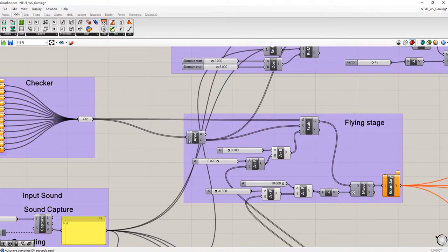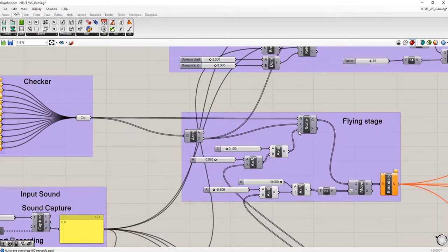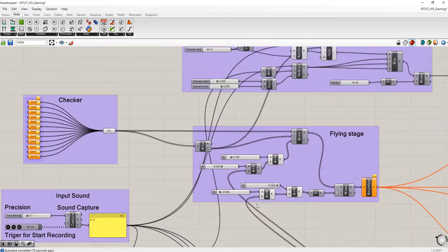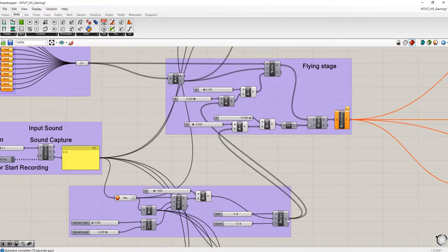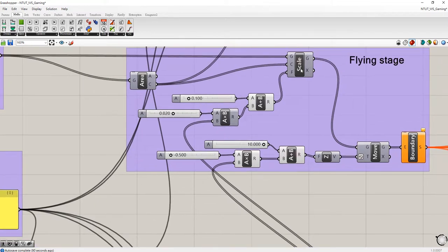So first thing, I use an area, and why I use an area, because I want to extract the center point of every curve. Okay, and then use the center point for scaling. Alright, and for the scaling factor, I do it this way. First, I connect the number to here, but I still do another adjustment, and this one is 0.02, and I add on a base minimum number, because sometimes it will become 0. So I add on a minimum number of 0.1 and connect this part to the scale.